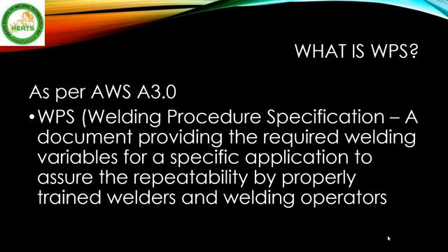As per the definition of AWS B3.0, a WPS is a document providing the required welding variables for a specific application to assure the repeatability by properly trained welders and welding operators. Meaning, if you have a WPS, you can use it repetitively to have good and sound welds.